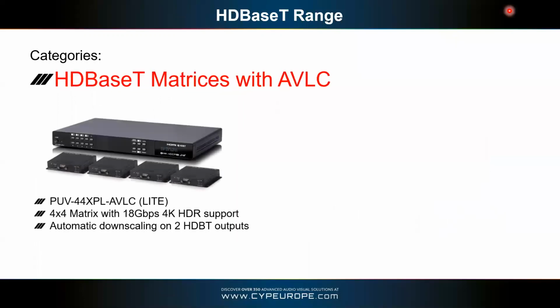And let's have a look as well. You've then got models that have the AVLC technology. So these are then matrices that can handle 4K HDR. So again, we have a 4x4, 4 input, 4 output. This unit as well, 2 of the outputs on this 4x4 HDBaseT matrix, 2 of those HDBaseT outputs have automatic downscaling. So if the customer is combining 4K and 1080p screens in a property, you don't need to buy separate downscalers. This will automatically downscale on 2 of those zones if it needs to.